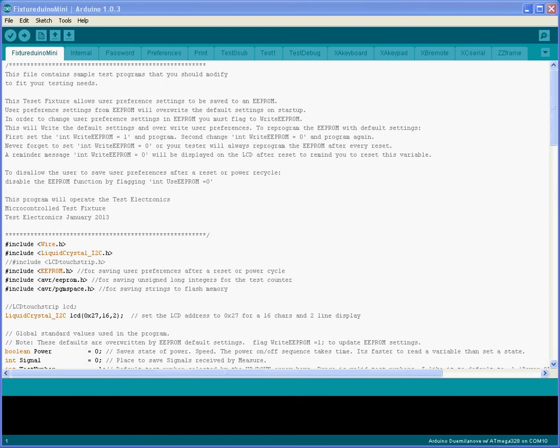Flash memory has 32K of memory. 1K of the flash memory is used by the bootloader. 31K is left for us to store text arrays and text strings in, versus the old 2K that we had to store in static RAM. Now we have 31K, which gives us a lot more opportunity to store prompts, text strings that have to go out to the LCD display, enabling us to make much longer test routines.